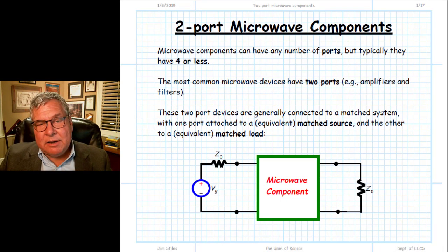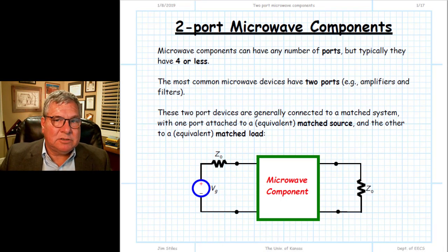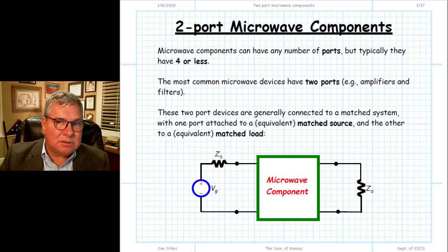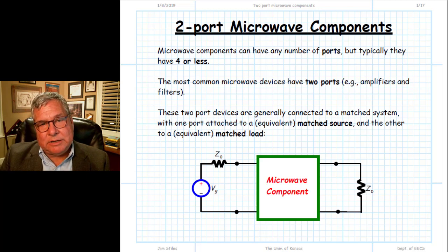When we speak of microwave components or microwave devices, RF components, RF devices, what we are implying is that those devices are matched devices. They were designed to work within a matched system, generally speaking 50 ohms, meaning they are built such that their port impedances, either input impedance or output impedance, are numerically equal to Z0 if all other ports of that device are connected to other, quote-unquote, matched devices. And so again, we need every device to be matched.